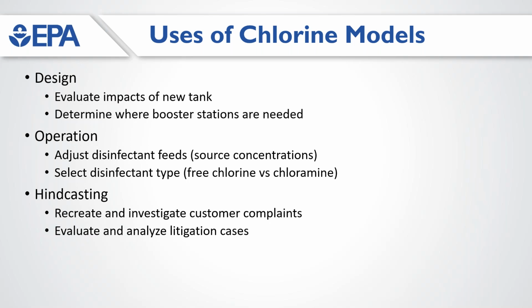Unlike water age, it is also used for hindcasting. You can set the model up as it was in a certain scenario and simulate what happened and figure out how and why that happened. This is useful for recreating complaints, like a customer's tap smelled more strongly of chlorine or something. And in litigation cases, chlorine modeling can help determine if something in the system was not meeting the legal requirements.